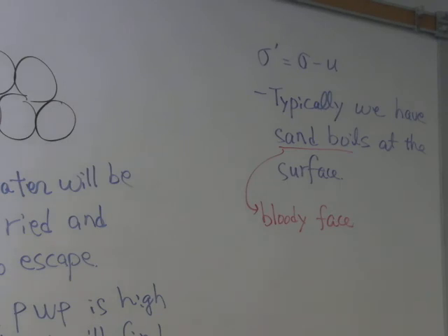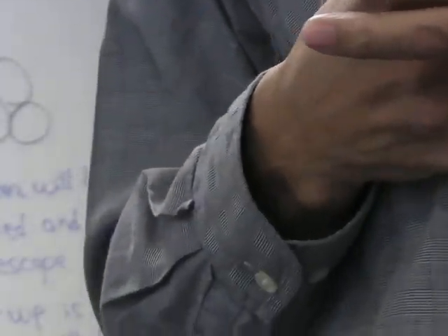And I think it's about the time. Well, is it about the time? How long does it take the pore water pressure to dissipate? Like hours, days? It depends. If your soil has very high permeability, it's not going to take a long time. If your soil has mostly clayey soils, it will take a long time to dissipate.